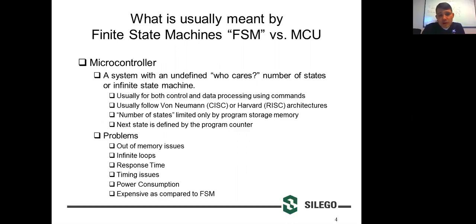And that's one thing, is what happens when you run out of memory. If you need to store a lot of data and you don't have anywhere to store it anymore, that can create problems. If you are storing program memory and data memory in the same physical memory locations, you can have accidental overwrites, you can have stacks that overflow. You can create infinite loops like we were talking about really, really easily.